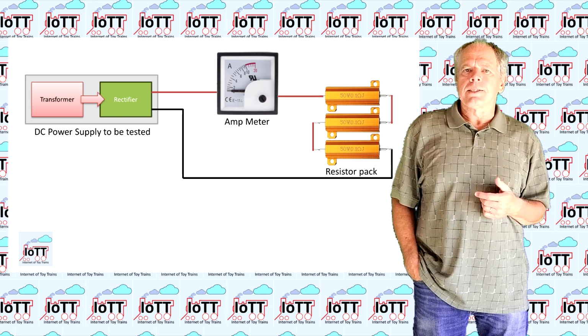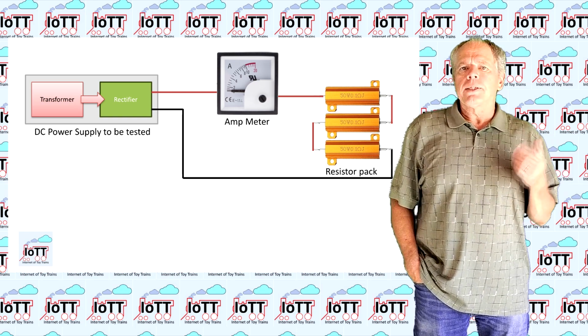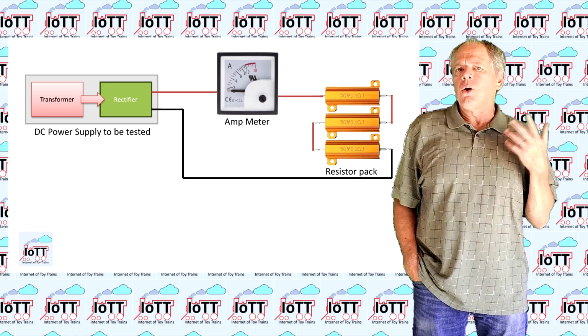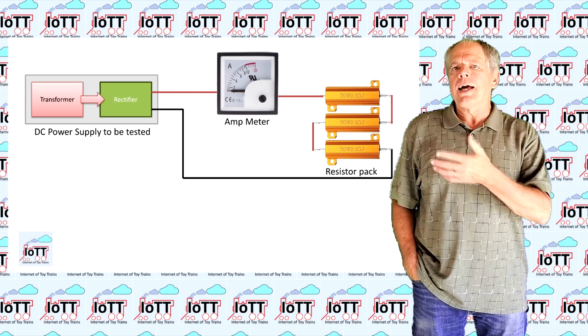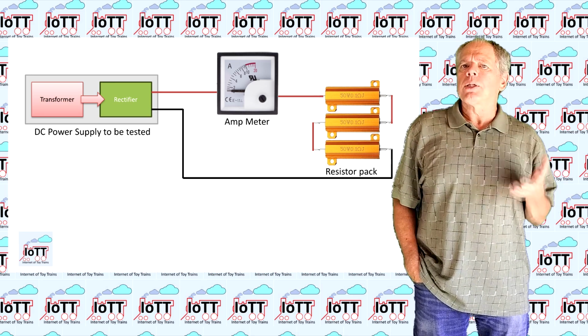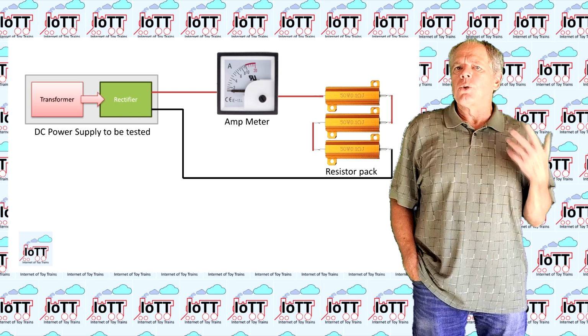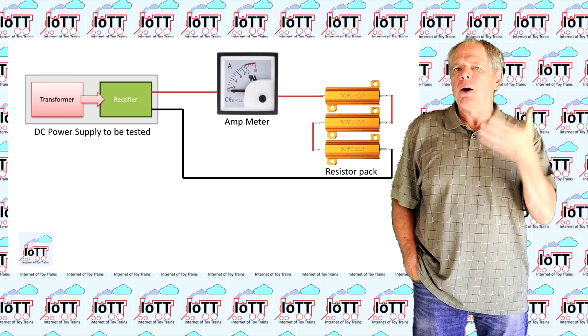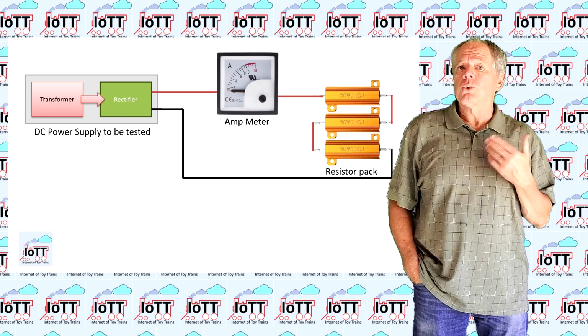Using ohmic resistors is, by the way, pretty much the worst case scenario to load a digital command station, as the ohmic resistor causes a continuous current flow the entire time. This is much more demanding for the power supply than a locomotive load, which is normally just a series of brief pulses, as the decoder also uses a PWM pulse to drive the motor.